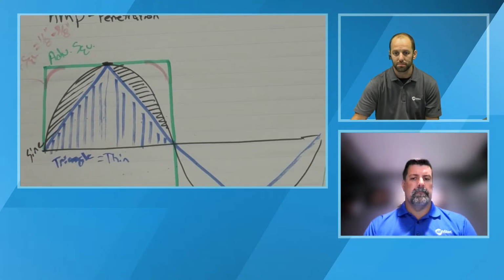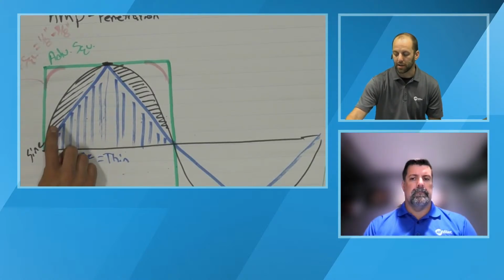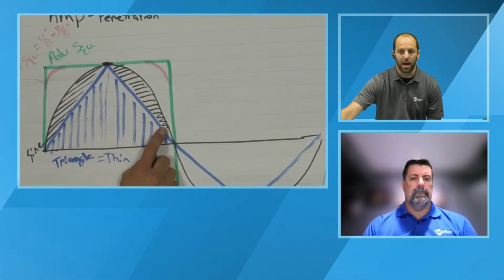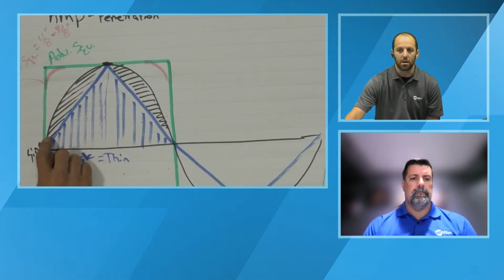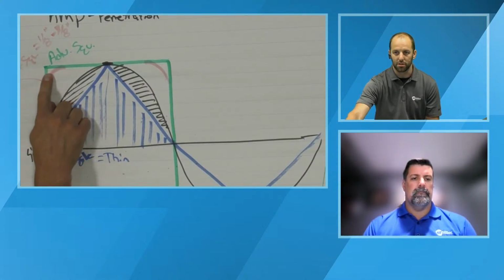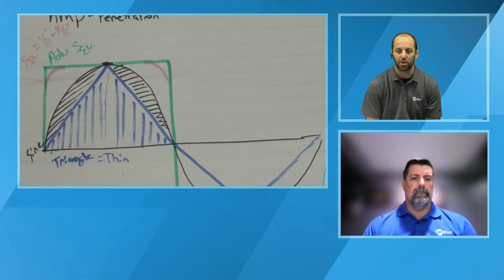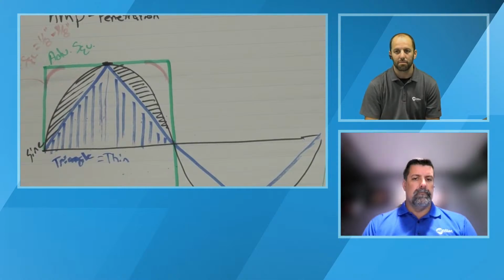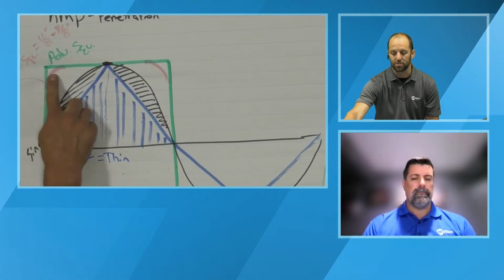Now, when we look at a sinusoidal waveform, which was common on traditional equipment, it gives you a little bit more heat. We still have options in the power sources for that, but the most commonly used is going to be the green square, or the advanced square that's drawn on the paper here, or my personal preference, where we round those corners off. That gives you the soft square waveform, and that's good for 1/8 inch up through about 3/8 of an inch or so materials, and gives you excellent results.